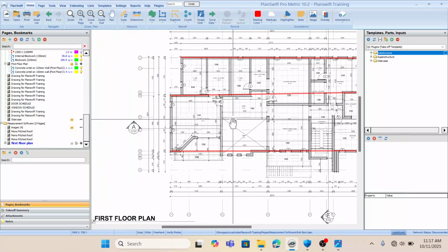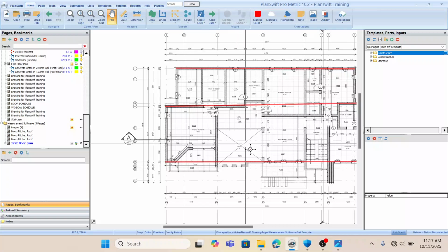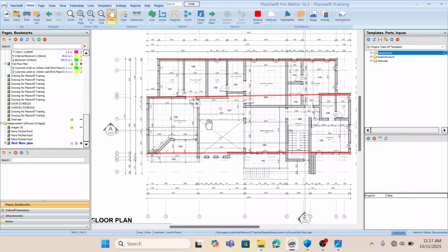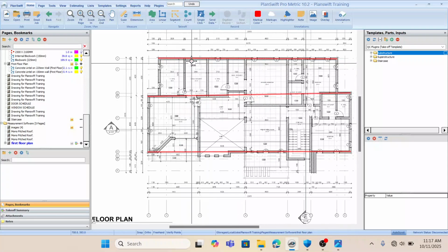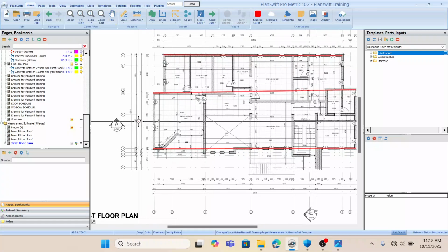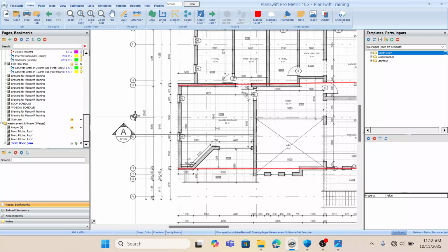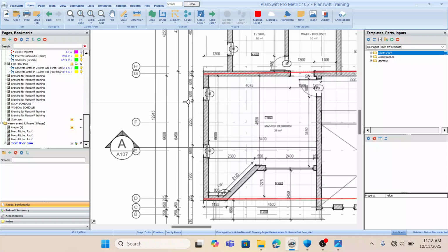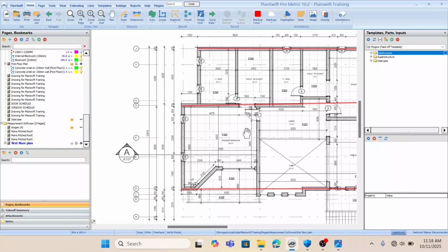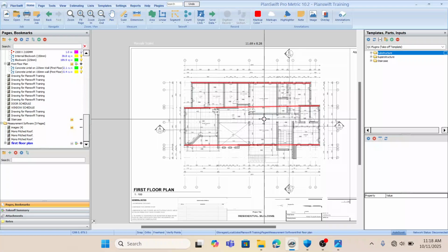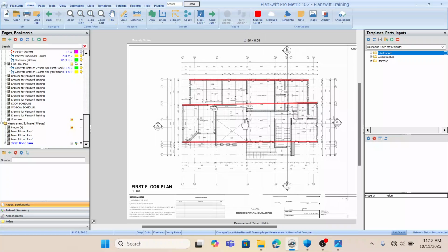But for most structures, once the width or the distance is more than 12 meters, especially for industrial buildings and all of that, it's usually advisable that you make use of a steel roof instead of a wooden roof truss. But I want to have this on the plan. It's wood, not steel. So I'm going to measure it that way.